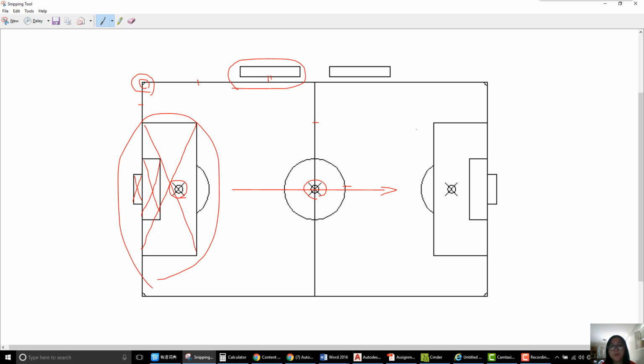In this drawing, to finish each geometry, there are always multiple ways. For example, to draw all the box, you can use the line command to draw continuously. Also, you can use the offset command to offset the touch line and goal line, and then trim them off. So mine is not the only way to draw the soccer field. You can feel free to explore other possibilities. Okay, let's start drawing in AutoCAD.